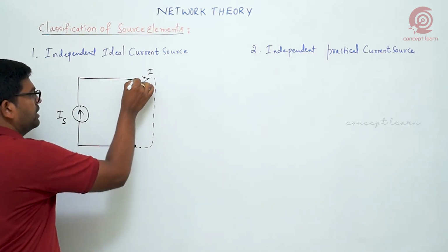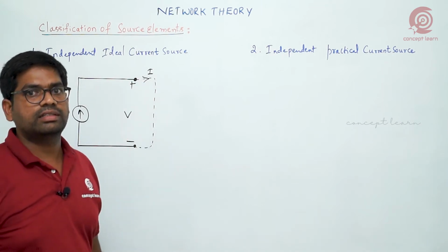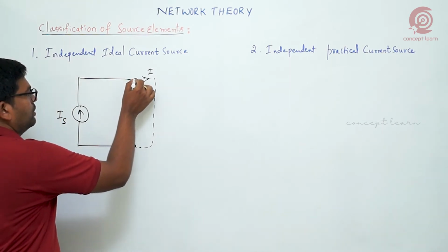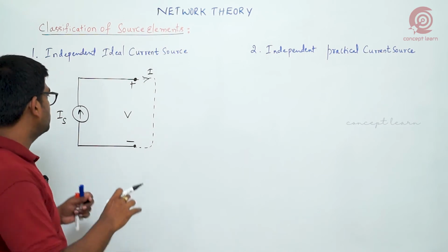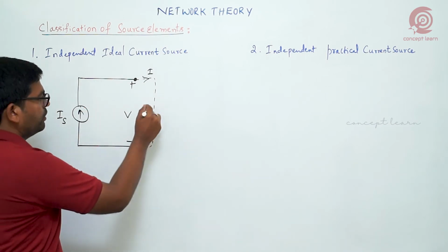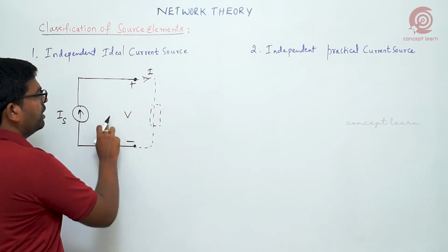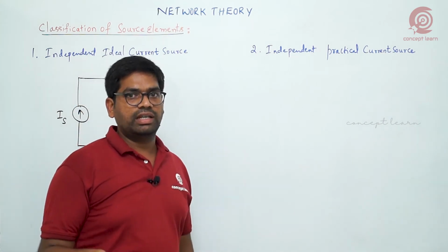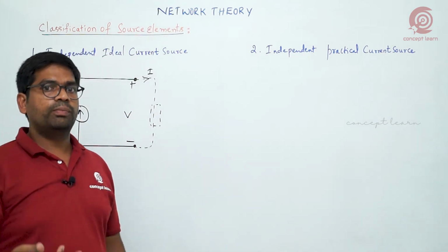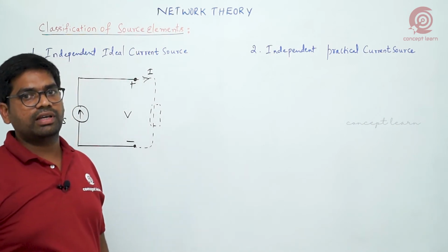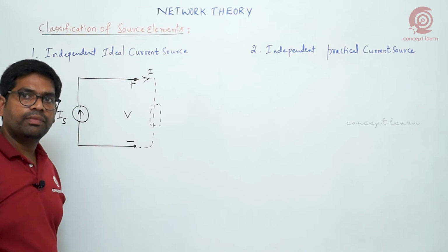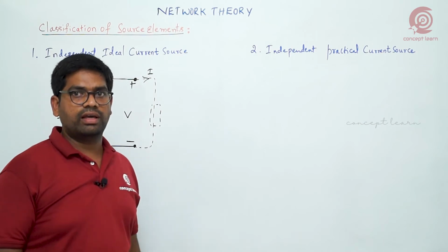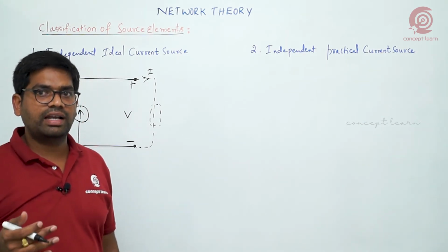At this moment, as I said, KCL is also not discussed, but we need to use that. Here a node or a point or junction is present because it is a source, one element, and when you connect another element here, a common point or junction is there between two elements, a node is present. Node means you can apply KCL. Loop means we write KVL. Here node means we are applying KCL. What is KCL? At a node, the algebraic sum of either incoming or outgoing current must be 0. But what is the standard statement?